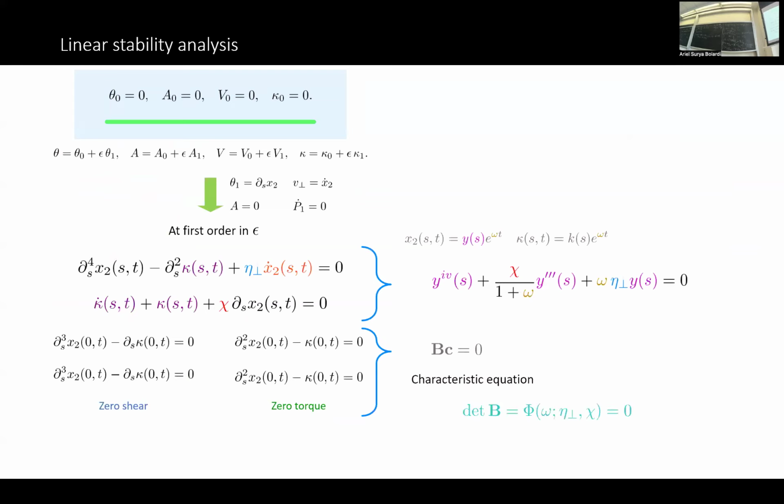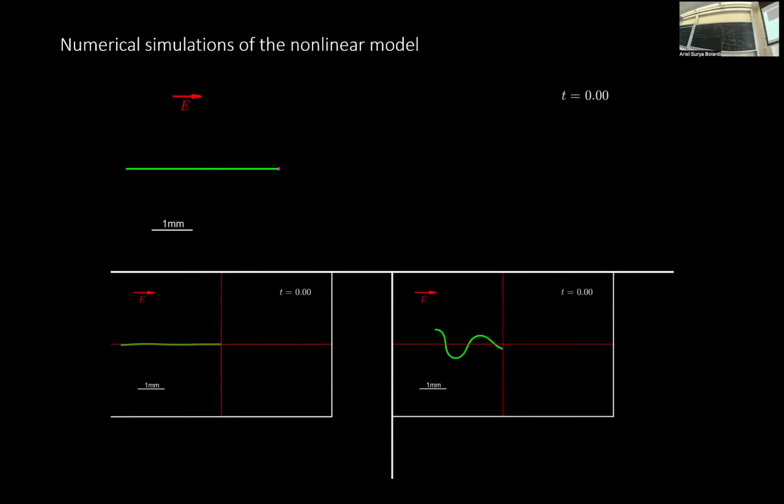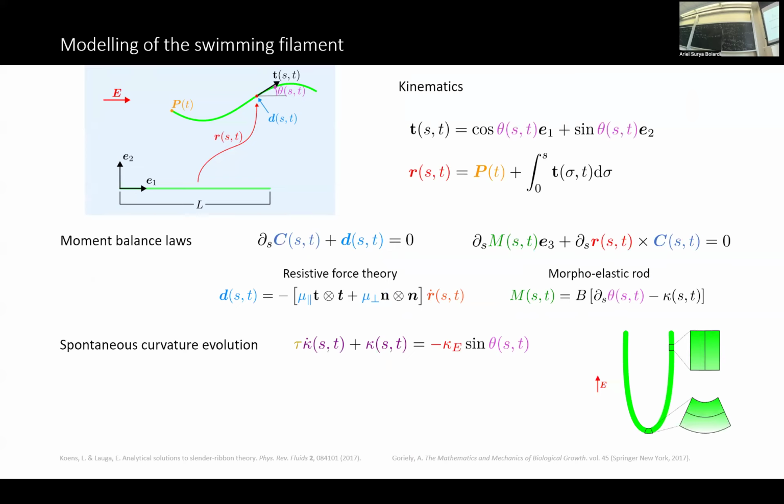Good question. One model of what's happening is that something causes the mobile ions to migrate in the cross section of the ribbon, and this causes a difference in volume of the two sides of the cross section, which causes it to bend. And that's how the internal moment is generated.